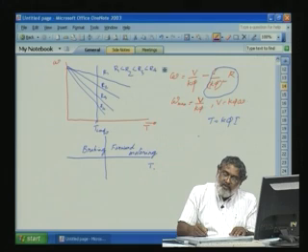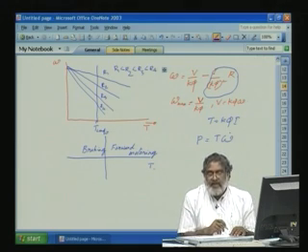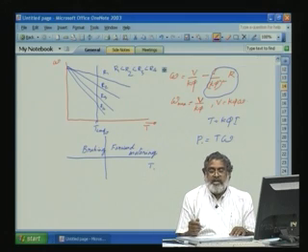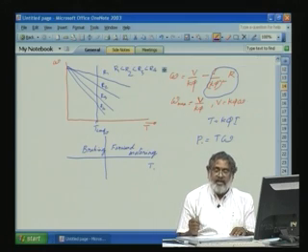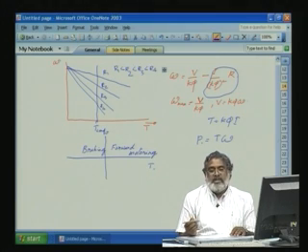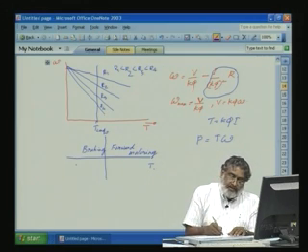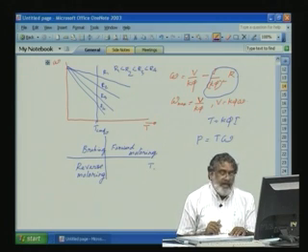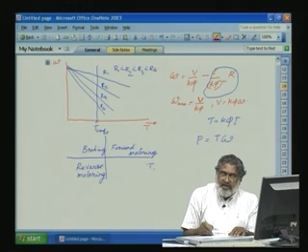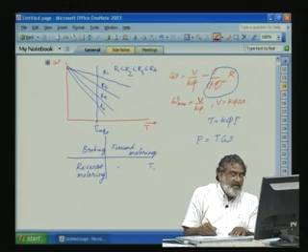We know P is equal to T into omega. So, when both the torque and omega are negative, that is, speed is reversed and torque is also negative, then power is still positive. That means it is called reverse motoring, same like our forward motoring. This is called reverse motoring. Now, in this case, torque is in the other direction, so it is called braking.